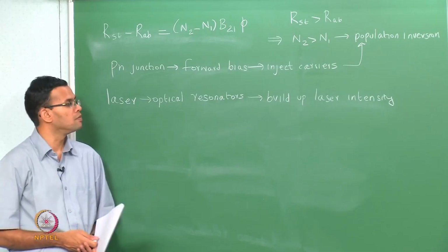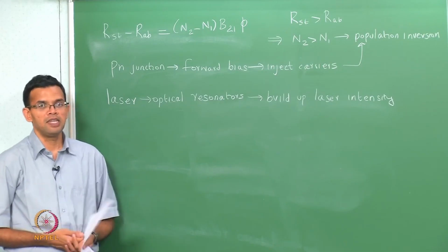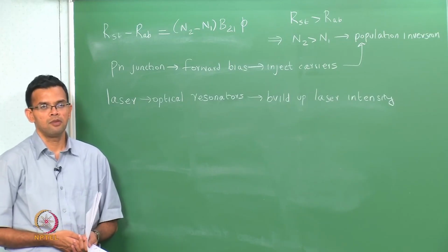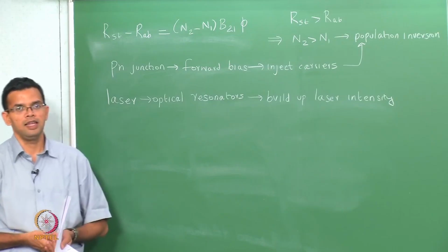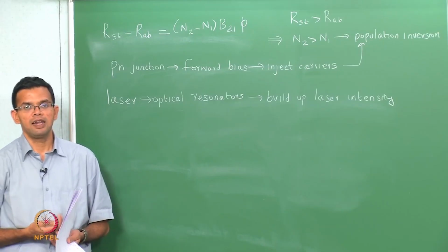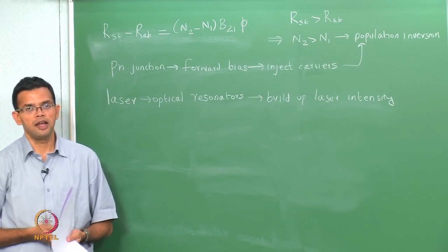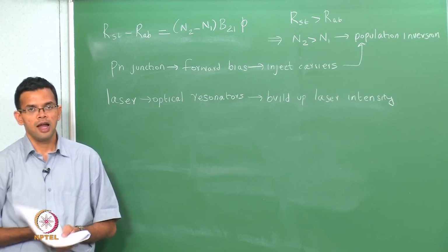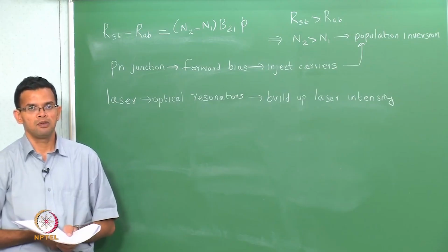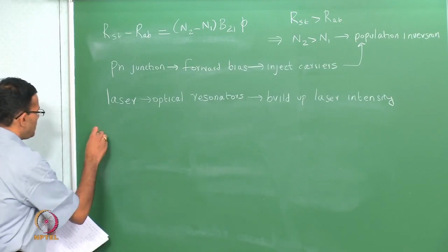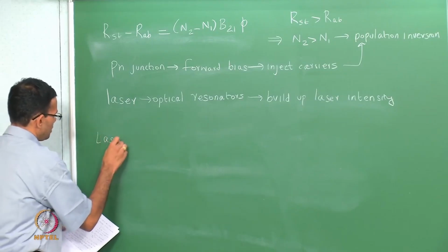one side. Now, if you look at materials that we use for lasers, these are very similar to the materials that we saw earlier for LEDs. They have to be direct band gap materials, usually some sort of a graded heterostructure is used, and depending upon the band gap, the wavelength of the laser will be determined. So, some examples of laser materials: